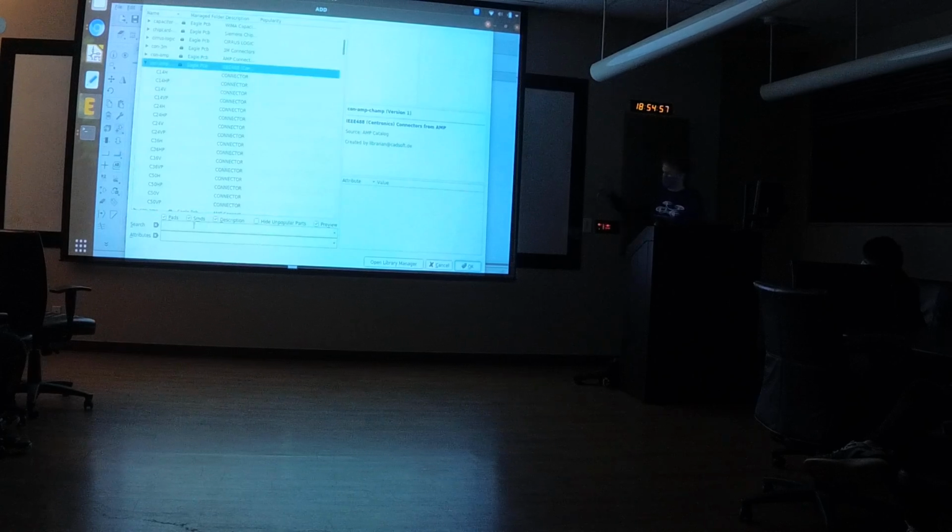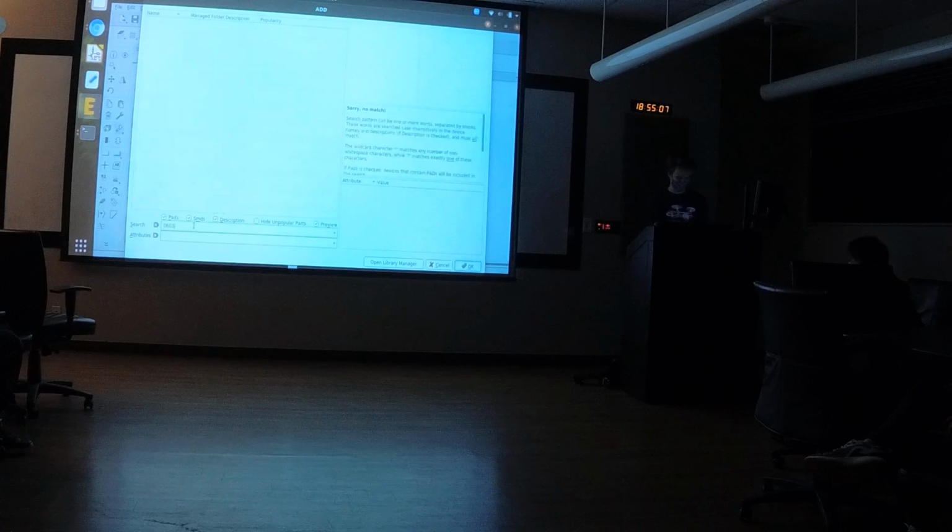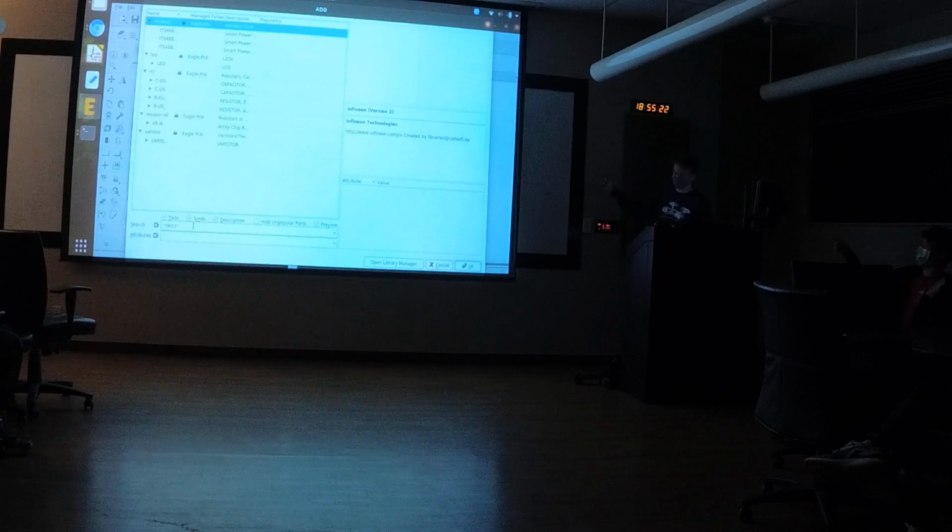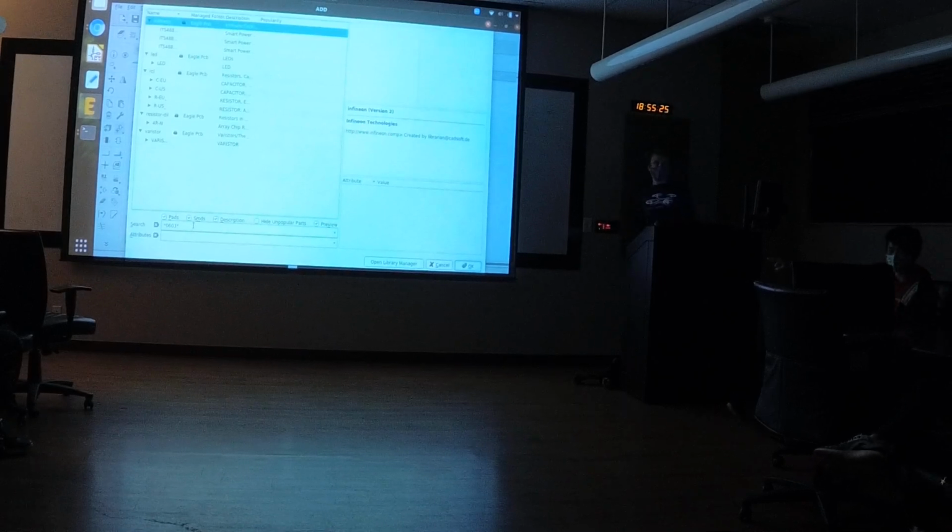That's kind of hard to do, so we can search for stuff. The way you search for stuff in EagleCAD, in my opinion, is really stupid. You can search for an exact string by going like this. See, it says sorry, you don't match, which doesn't make sense. There must be a bunch of 0603 capacitors in here somewhere. Where are they hiding them? That's because you have to surround your search terms in asterisks. Why? Don't ask me. There are a bunch of search tricks with underscores and ampersands, every symbol you could ever think of that filter out specific sections. Yeah, the search is stupid.